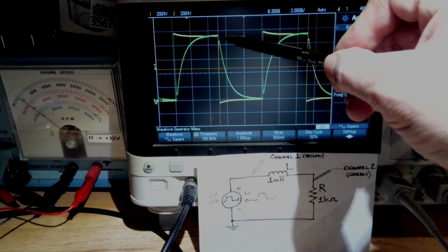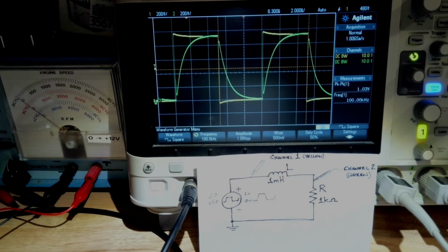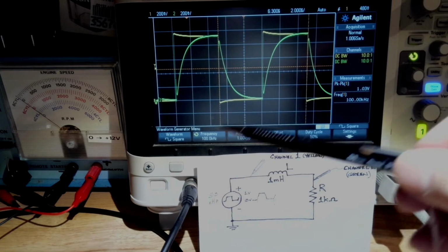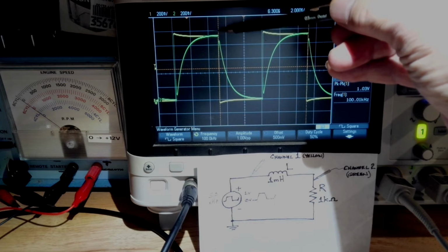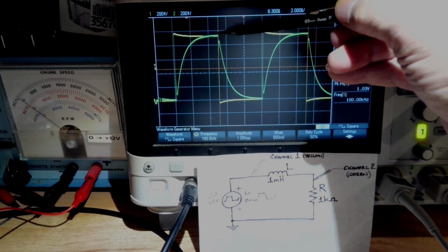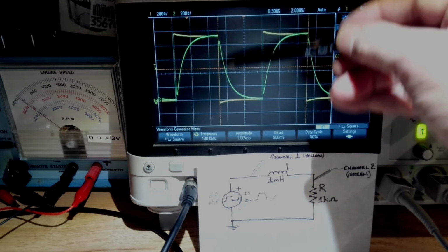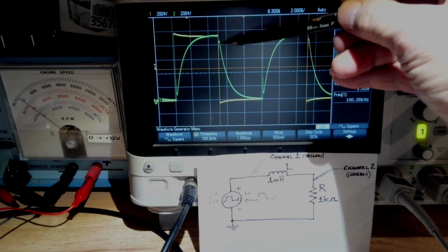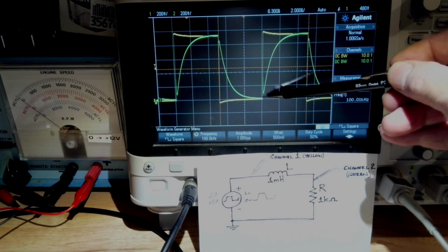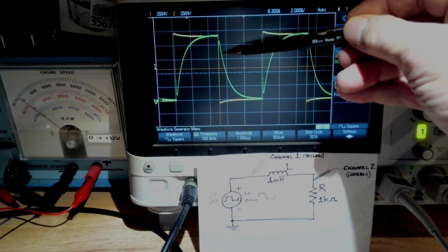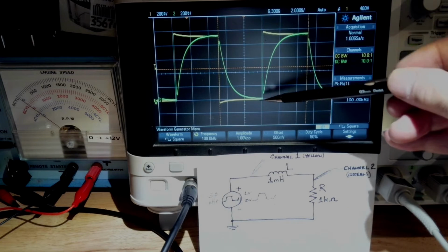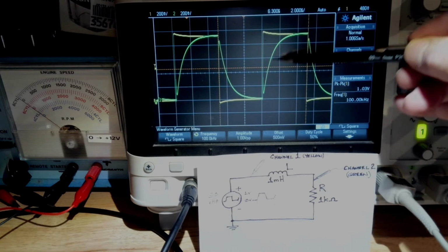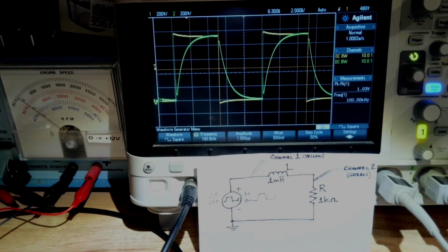But the inductor has a magnetic field built up in it, and that magnetic field is going to collapse, generating a back EMF in the inductor that fights you. So the inductor current won't drop immediately to 0. The inductor current will come down as the magnetism dissipates from that coil and gets near zero, and then we turn it on again and it does the same thing, and off again, and that sort of thing.